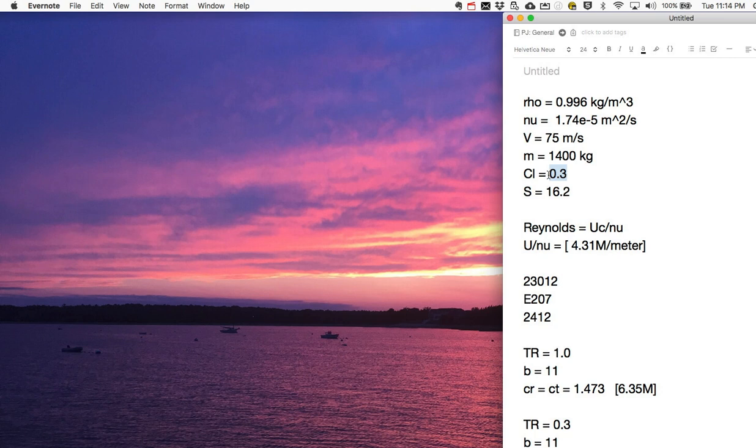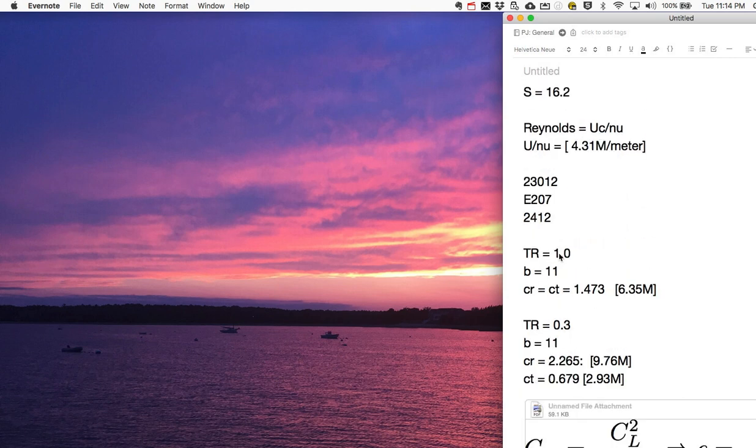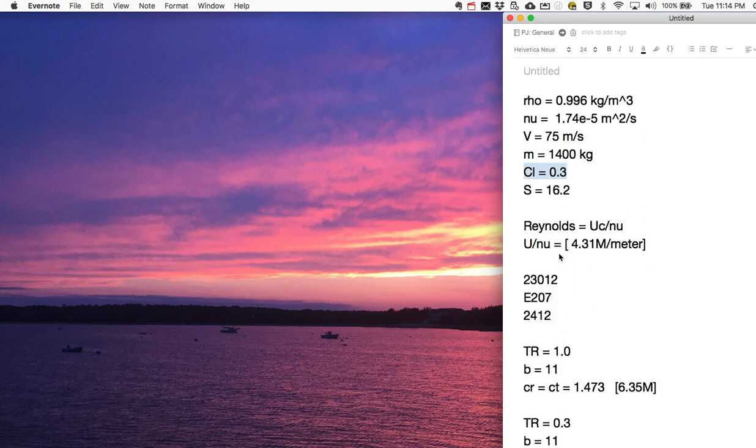Now the lift coefficients of those sections will not deviate greatly from the lift coefficient of the whole wing. It'll be slightly more, say at the most 50% more, and down towards 0 at the tips. And so I need to be able to have a range of lift coefficient for my polar of, say, I would want to say 0 to 0.5. I also want to have the right range of Reynolds numbers.